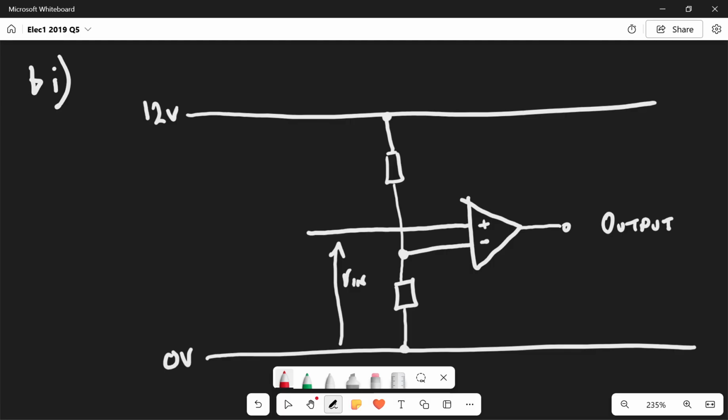Well, the first thing we need to ascertain is, is this a light sensing or a dark sensing circuit? Well, we're told that when the light level falls too far, the comparator output switches to positive saturation. And we know that the resistor and LDR need to be attached to the non-inverting input. Well, what this means is that it must be a dark sensing circuit.